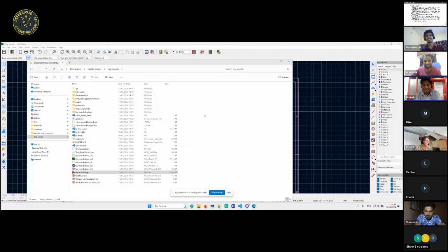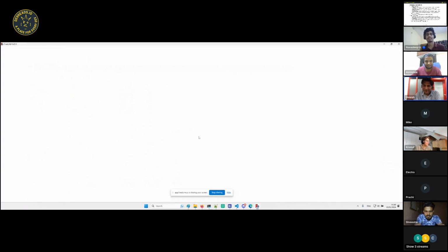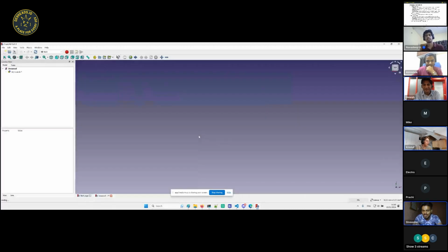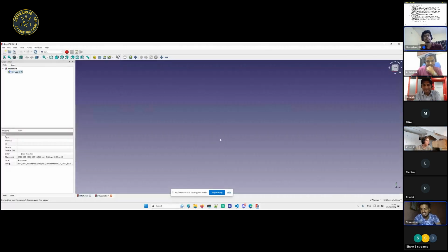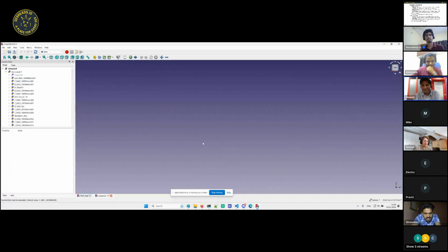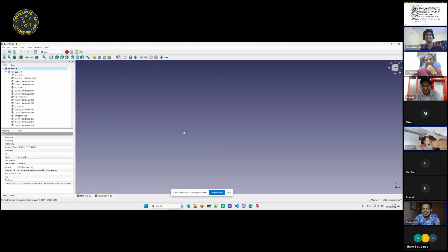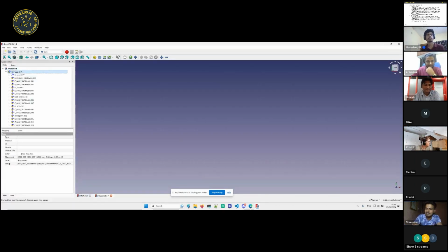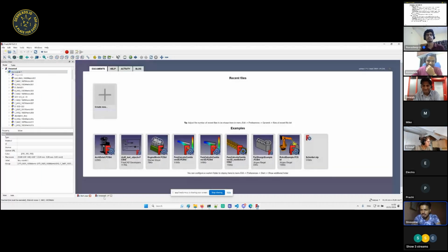And I think it usually generates with the Gerber files, doesn't it, with KiCad? I don't think so. It's just Gerber files. Like all the layers, and you have to generate the drill files separately. Everything separately. In Altium, it generates everything as a part of the manufacturing files. Altium is a pro tool. Yes, I think you have to select all. I thought so, because I have generated a step file once, but I don't know if anything else is required, like to tick mark.